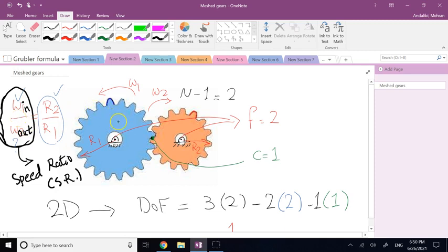If the input is coming from the engine, then the output that goes to your tires, your wheels, will be different for different types of gears. Low gears will give you a smaller output, so the car goes slower, but you get more torque. High gears make the output turn faster, so your car goes faster, but you get a smaller amount of torque.